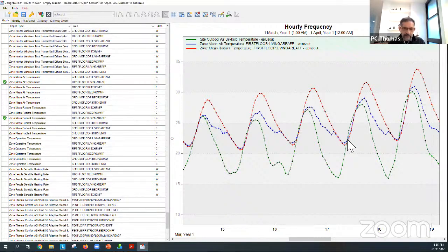Okay, so you can test that using the natural ventilation thing. And what we've done is we've left the windows open the whole time, at 50%. Now, one of the reasons the temperature is not coming down a lot is because I've actually changed the ground temperatures.